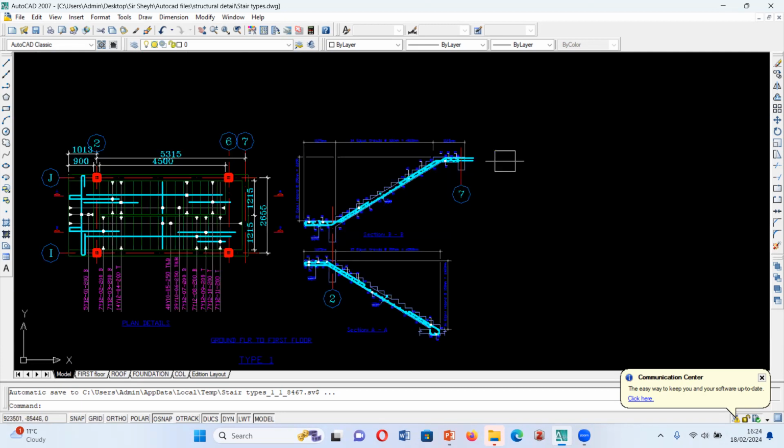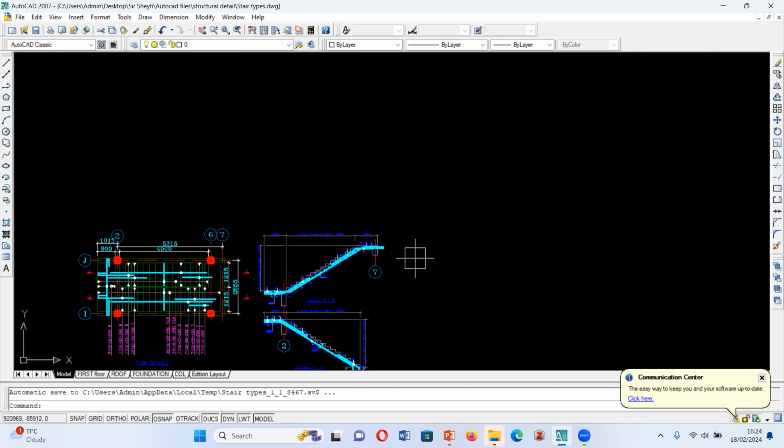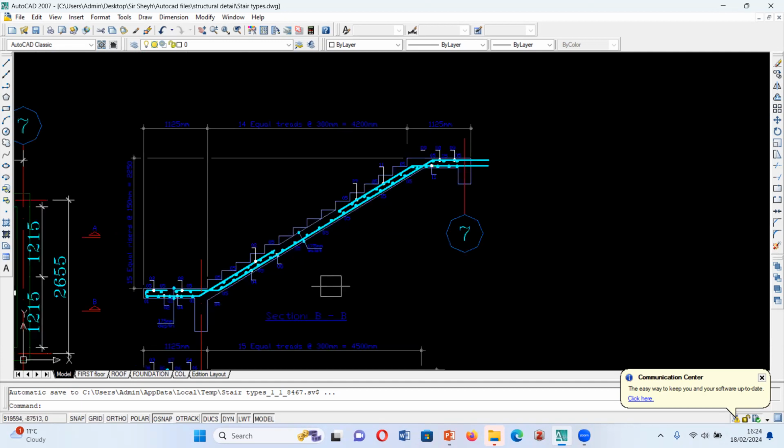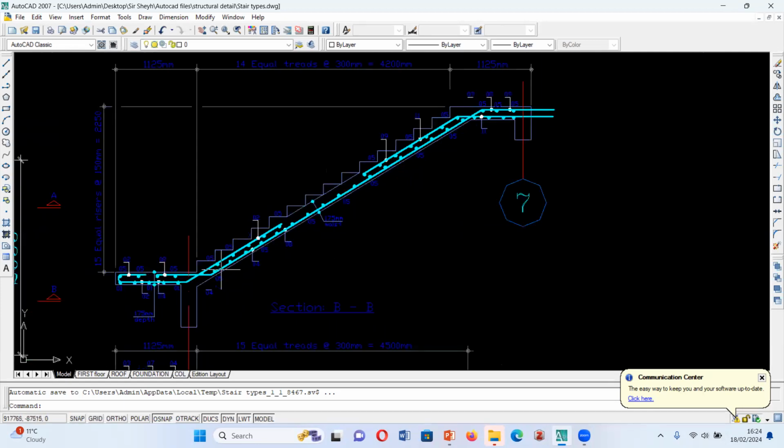Okay, so I just have to say that about that. You understand? And let me also say categorically that your waist is a very, very important factor when you design your stairs. And let me sound a note of warning, most especially to a lot of carpenters out there. You're going to see that a lot of carpenters would make a formwork that would give you a good depth of concrete or a good waist towards the start of your flight.